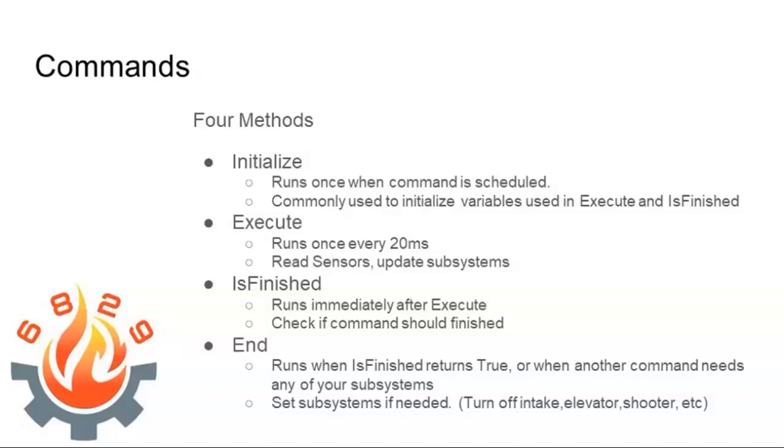But anyway, initialize. Initialize occurs as soon as you push the button and the command is scheduled, it runs. You use it to set the logic state inside the command to a known state, right? A common thing you might do: let's say you wanted to drive forward 5 feet when you push a button, the encoder value is what you're going to use to figure that out.